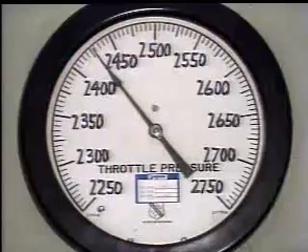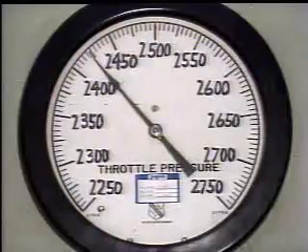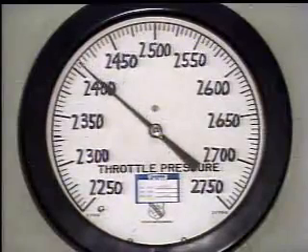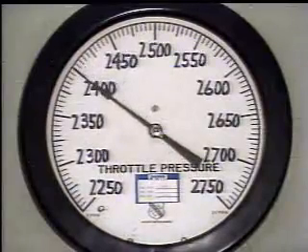The loss of fire or flameout in a boiler is an emergency condition that requires immediate action. Frequently, operators can see the flame directly from the control room or on a television monitor. Some boilers have flame scanners, which are electronic devices that monitor the flame. If a flameout occurs and immediate action isn't taken, steam pressure drops. That's because the heat input to the water in the boiler has stopped, causing steam production to stop.